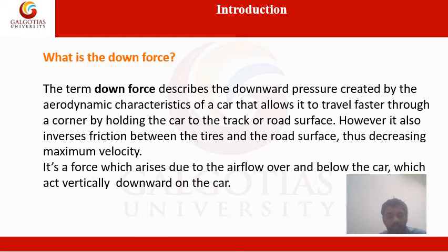So I'm repeating once again, take a note. Since it is a function of flow of air over and under the car, downforce will increase with the square of the car's speed, and it will require a certain minimum speed in order to produce a significant effect. I hope this sentence is clear to all of you.